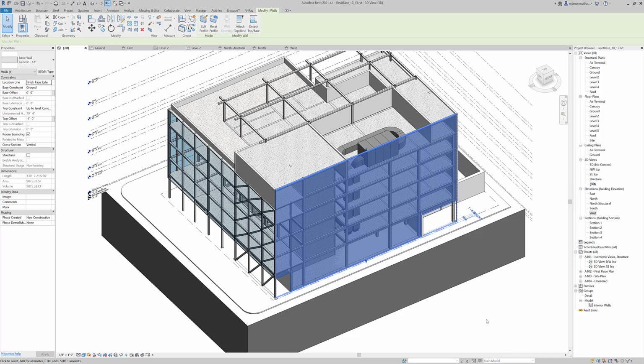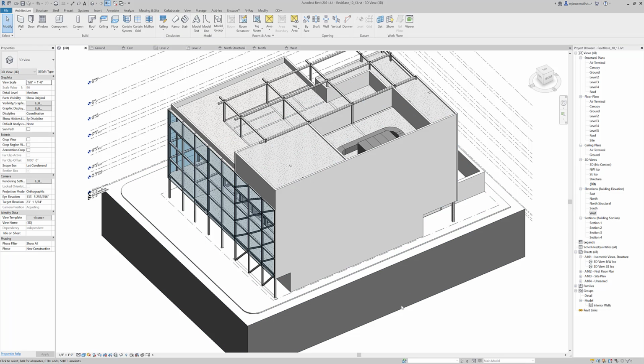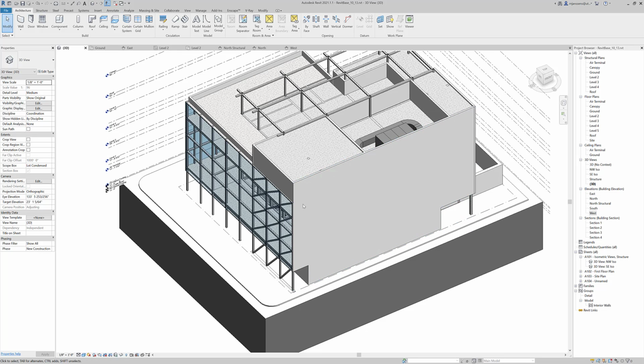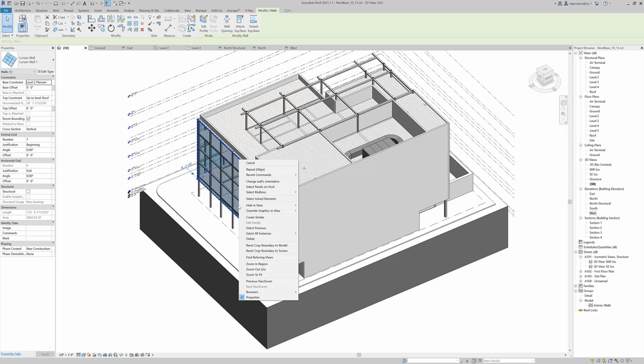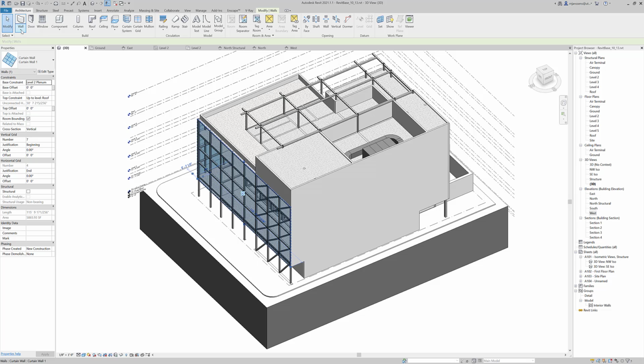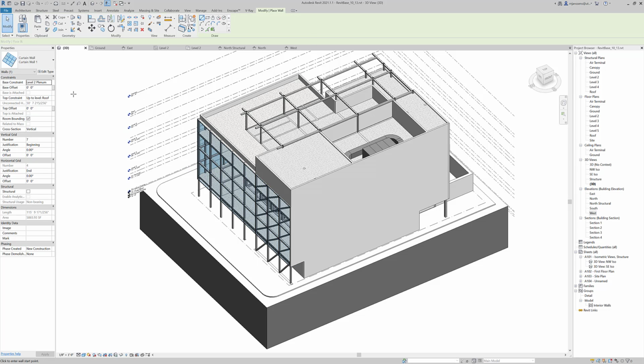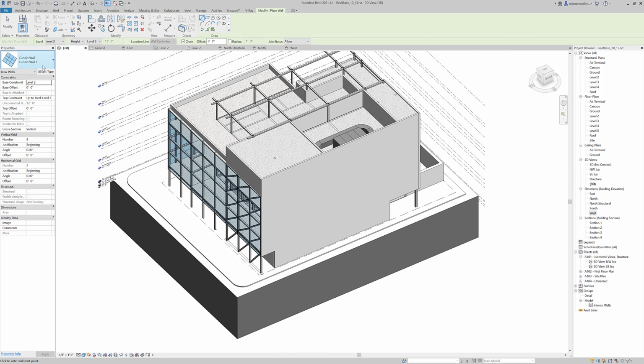It can be used to create a half window wall with sort of an opaque surrounding. It can also be used to create ribbon windows. So I'm going to show you the general steps that you would take here. The first step is to create a new family that will embed into this wall. You can select one of your systems and go to create similar, or you can go to architecture, curtain wall.